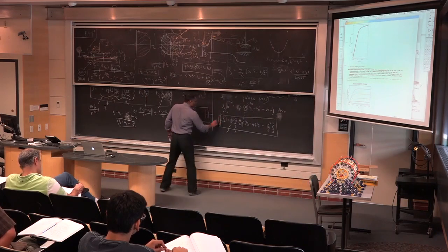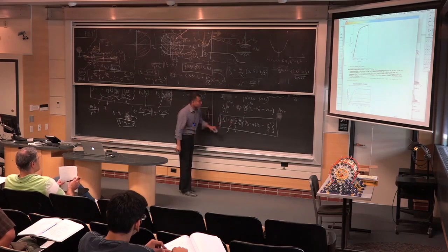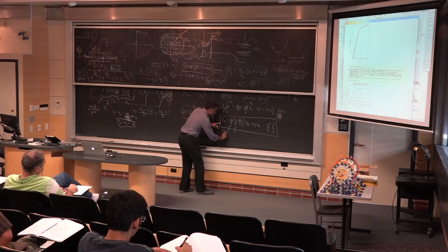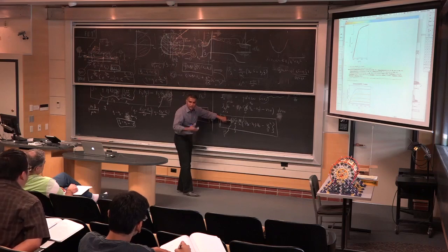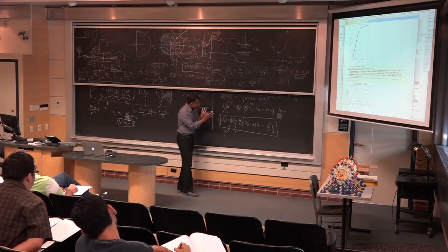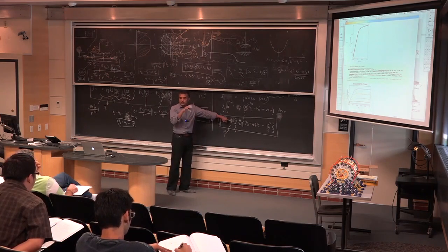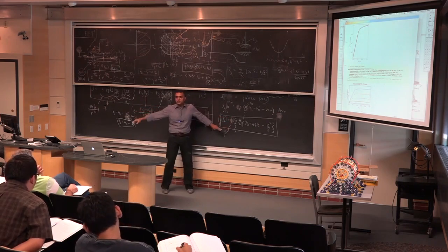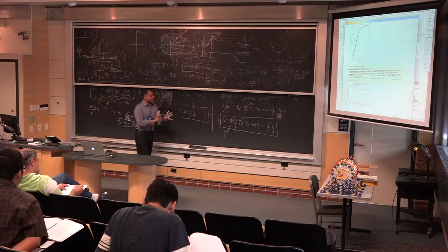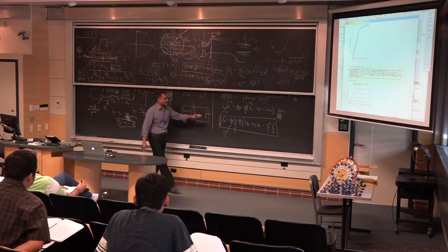But people were actually very worried when they were making transistors smaller and smaller and using this expression. Then you can do dID over dVd and pull out what is my mu. We measure it experimentally and pull out mu. People started observing that when the transistor got smaller, they thought there'd be less scattering, so the effective mobility should be higher, but actually the number they were getting was smaller and smaller. The reason is really nothing special other than that the model doesn't work anymore. It baffled people why the mobility was getting smaller, but it had nothing to do with the mobility, because that expression didn't work anymore.